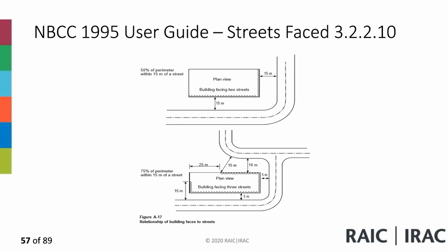Not area, building height. So you take the whole area, but each portion of the building can be constructed differently based on building height if it meets those requirements.